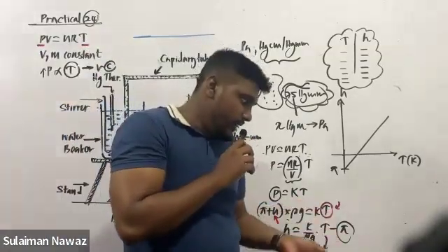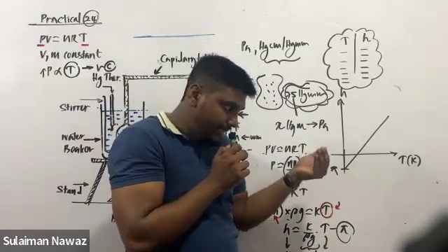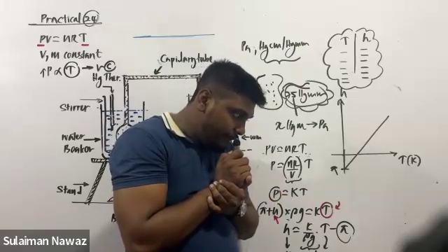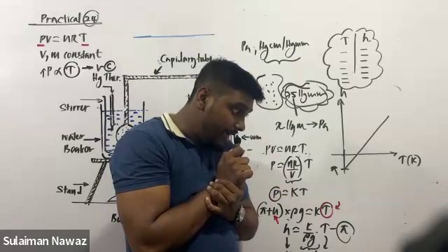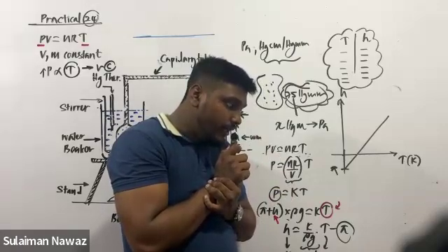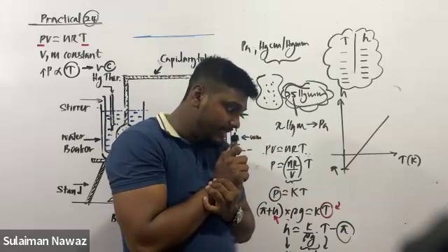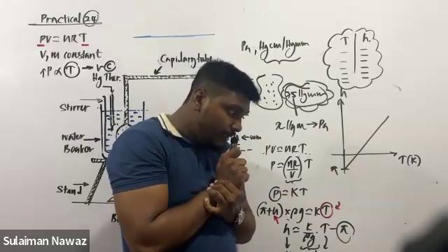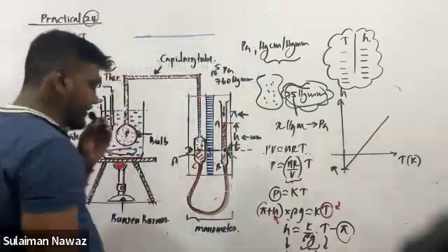Point number 5. Suppose readings are taken only during heating. Now when taking the final reading, since the height H is large, the bulb AB has to be kept in a higher position. If the burner has been turned off and one exits the lab with the AB tube in the same position, mercury may be drawn into the tube through the capillary tube as the system cools and the height decreases. To avoid this, care should be taken to keep the AB tube in the lowest possible position when leaving the lab.